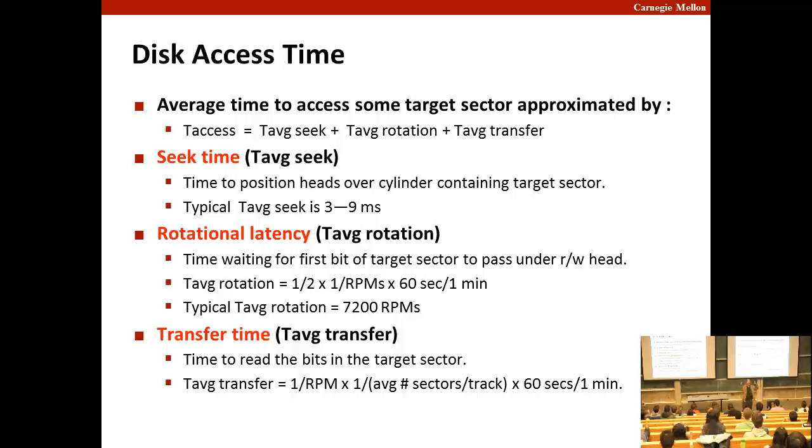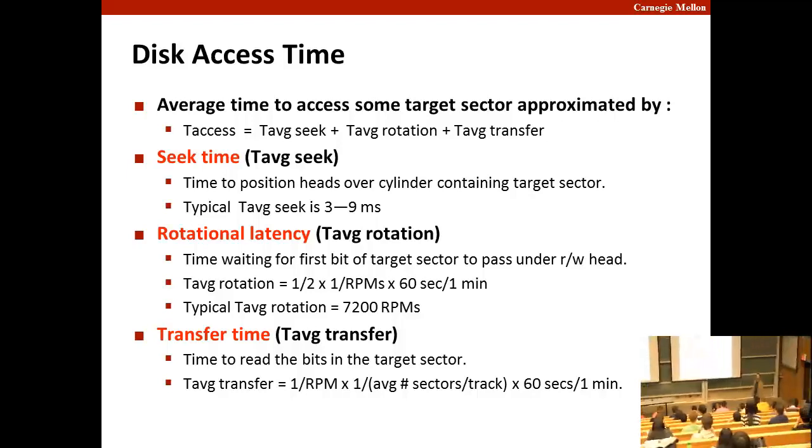It's not much faster than the full seek, because it still has to start and it still has to stop and still has to stabilize. So you might see a 10 millisecond full stroke seek and a 3 millisecond track to track seek, even though you might have many tracks. So you can talk about an average seek time, which is a little different than half of a full seek.